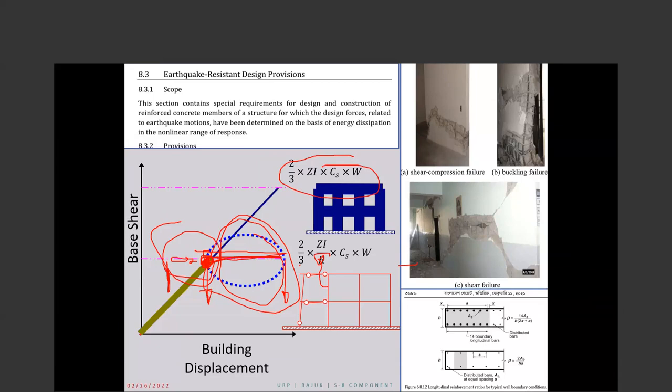Get damages. So you should model the building completely nonlinear. Check your design that none of those response parameters in none of the elements passes the ductility limit of that element. We should design like this, but we don't do that.